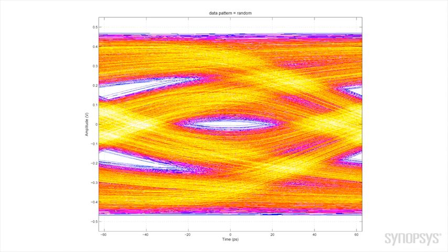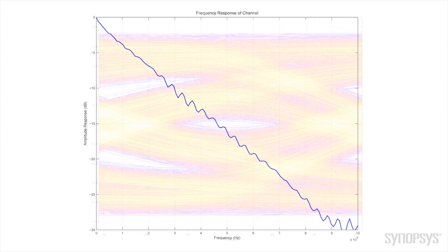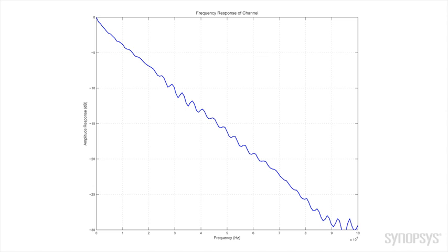Well, let's start by looking at this channel response. This channel response is just an example, but it shares something in common with basically any channel in a wireline data communication system: we see a frequency-dependent attenuation. So high-frequency signals experience a higher amount of attenuation compared to low-frequency signals. Now, why is this important?